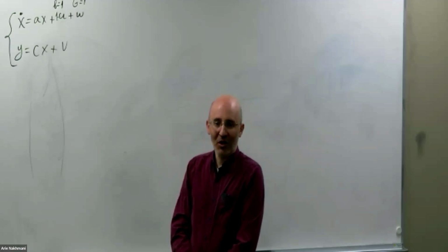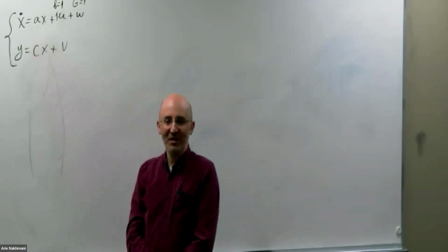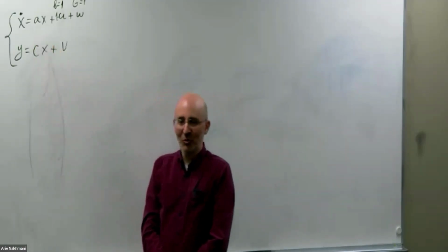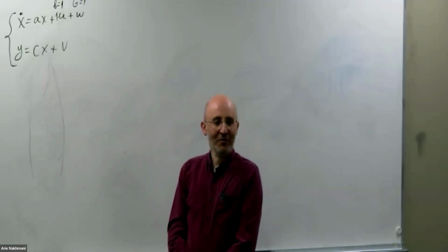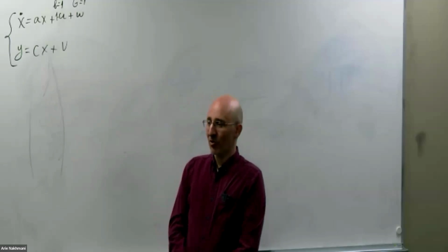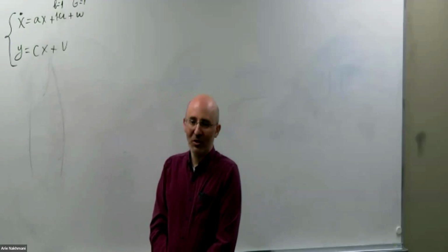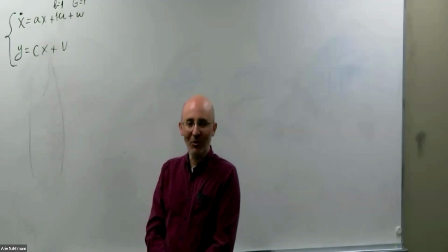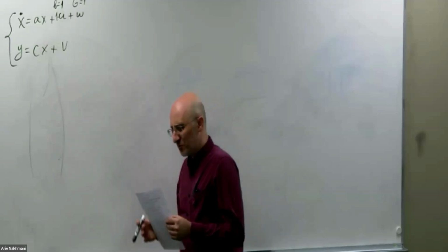Okay, so A is your eigenvalue. That thing is the eigenvalue of that system. If A is negative, then the system is converging to 0 as exponent of AT. Okay, this is how it works. So the system would be stable for negative A, and it will be unstable for positive A, or equal to 0, it will oscillate. Okay, that's what we know about that type of systems.